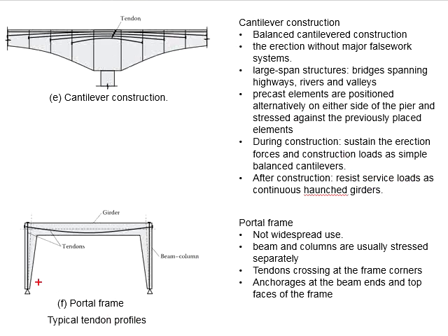Next, we look into the portal frame. You know that the portal frame with pre-stressing forces is not widely used, which personally I can't recall if I see any of this kind of structure anywhere. Nevertheless, it is still applicable. It is especially required when you require a large space within the portal frame, which is nearly not achievable by a typical reinforced concrete structure.